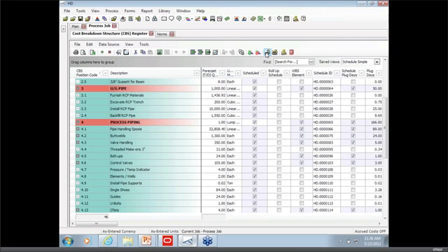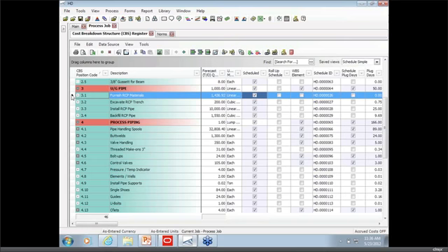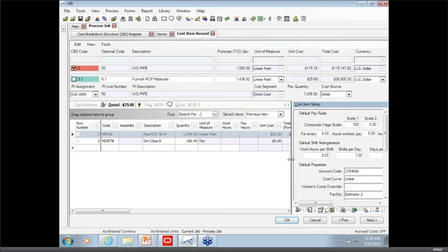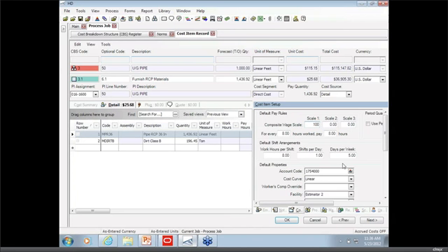Okay. Next question was, I have standard shift arrangements. I currently have difficulties changing certain items to a different arrangement, say 12 hours a day. Can each detailed activity be driven by a different shift arrangement? Yes. So I jumped into this item 6.1, and I'm looking at our cost item setup tab, and you'll notice on your screen that we can set a global default for the estimate. In this instance, the global default is working 8 hours a day, 5 days a week, and we're paying everything at standard time or scale 1.